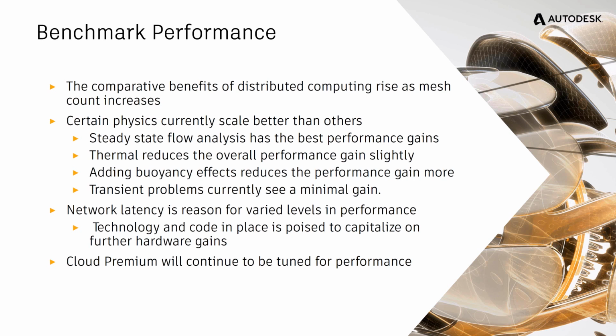Transient problems, we allow you to solve transient problems on Cloud Premium. Right now, the benefits are minimal. So it's really, to me, only if you want to solve a transient problem and it's just maybe too big for the cloud solution, then you might try the Cloud Premium. But for performance, not the greatest.